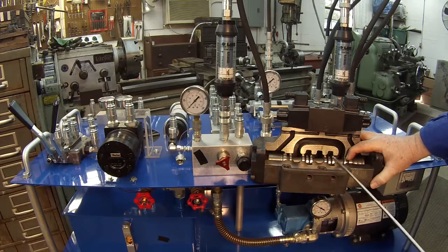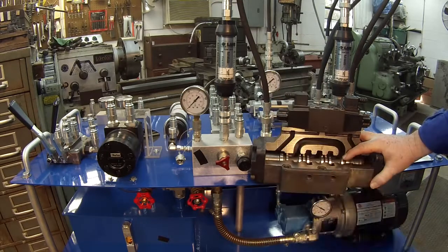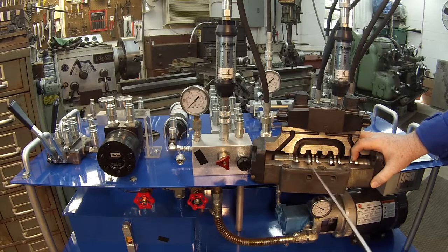So when I energize this valve, it opens up my P port to my B port and my tank port to my A port right here, and allows the cylinder to come in and out. When I de-energize it, these big springs like this push the valve back to the center position. When I energize it in the other direction, I've now connected my P port here to my other work port right here, and my other work port here to the tank line. Okay?